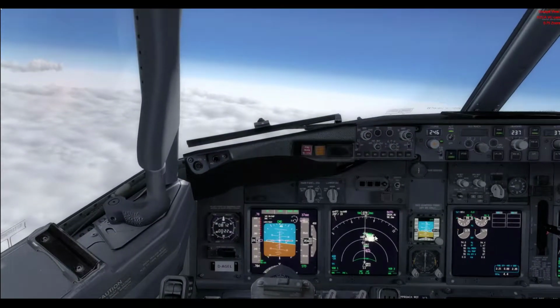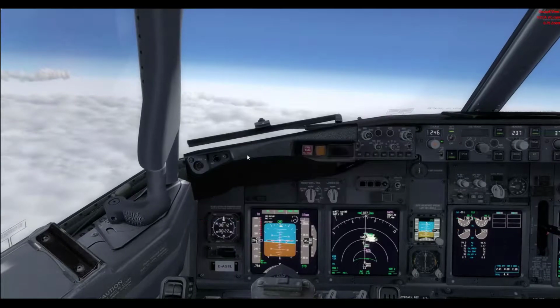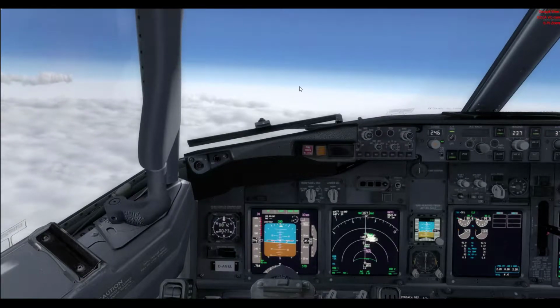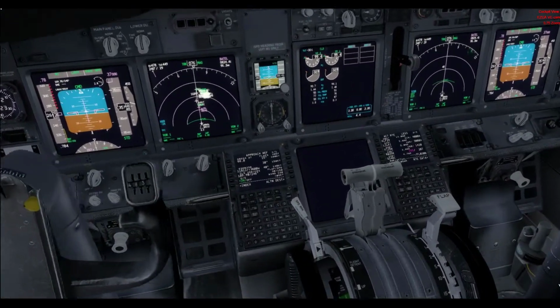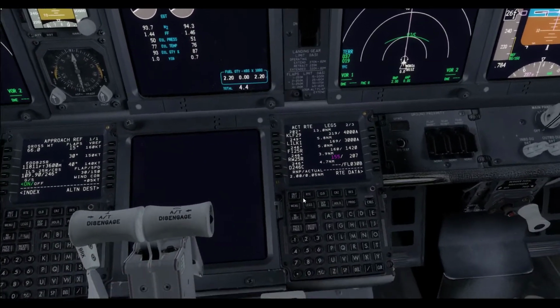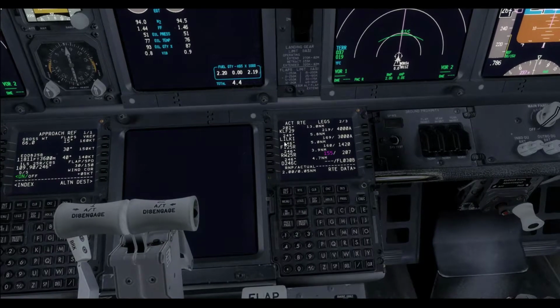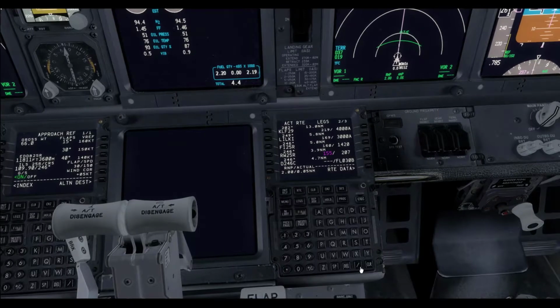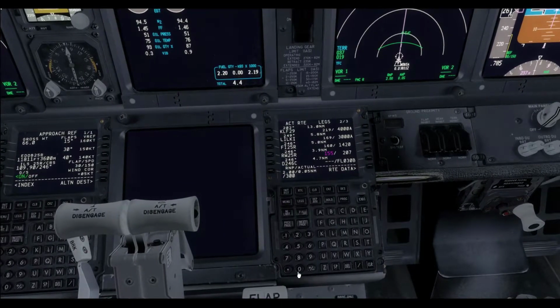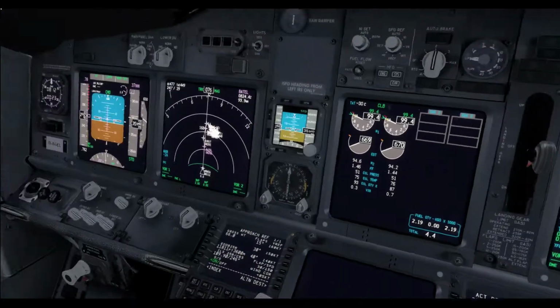Now we're reaching our top of climb shortly. And once you have reached the top of climb, you can put any altitude you want into this window. Now, usually you take your intercept altitude, so we take a look at the very last altitude restriction before you land. So this is at Lilki, 3,000 feet. At the moment it is 3,000 feet above, but to correct our descent path I will just put 3,000 in straight away.